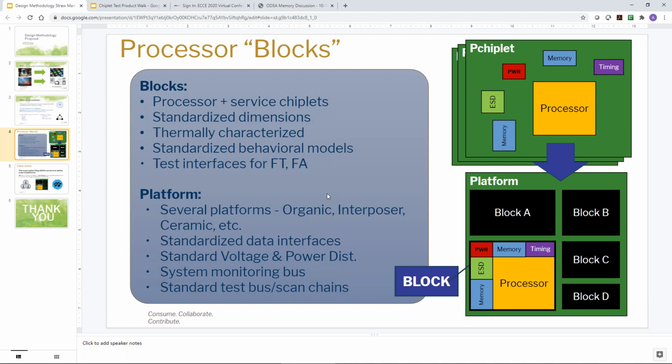I think what I'm seeing on the screen and what I'm hearing people saying, especially Ali, is that what Ali is proposing is an additional level of hierarchy to simplify the construction of SIPs. The level of hierarchy aggregates multiple chiplets into a block, the terminology Ali has chosen to use, and then you can come up with uniform shapes for those chiplets that you then coalesce into a SIP. Ali, is that what you're proposing here?